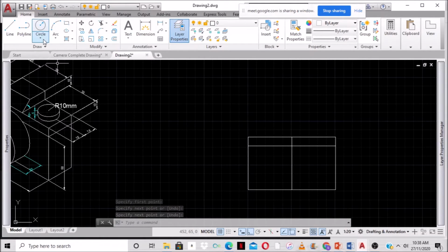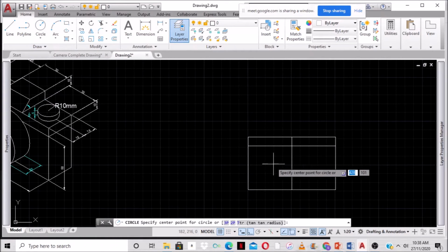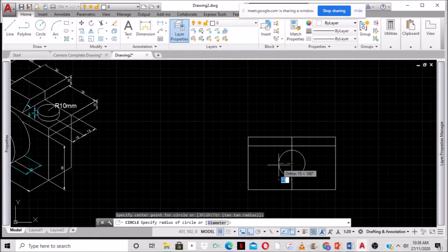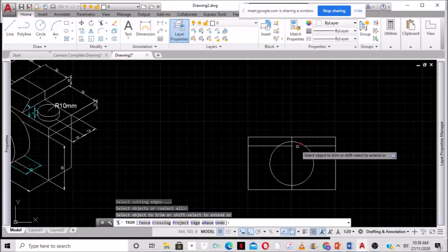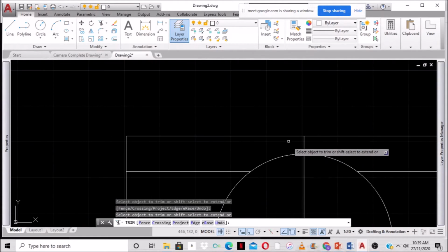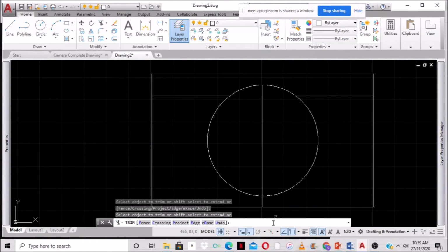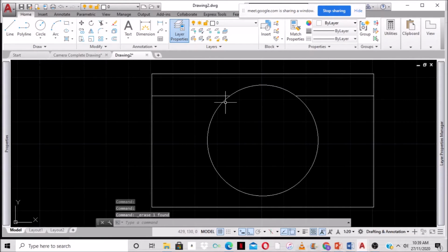Now, we just select circle and center radius. We come to the midpoint here, and we select, and we type our radius of 25, press enter, right? Now we can trim unwanted portion, so we type TR, enter, we trim here, and we can zoom up so you can see where you're trimming, you trim there, right? We also trim here, and then we're going to delete what we can't trim or erase. So we can just highlight the line and we erase, right?